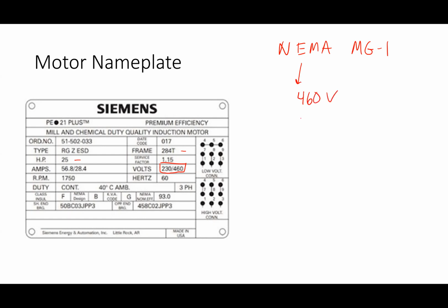Now, you may also have heard before, sometimes they talk about things being 110 volts, sometimes it's 120 volts, right? Basically, for motor ratings, they use a value a little bit lower than what the actual grid is likely to be, because I know the grid's going to fluctuate around. Why would you do that?